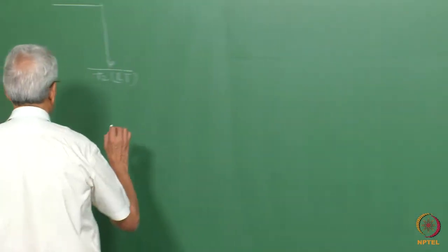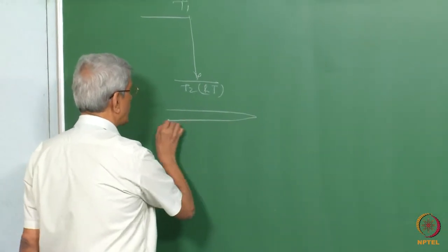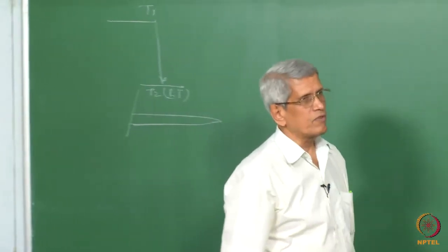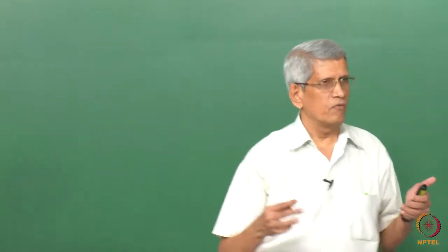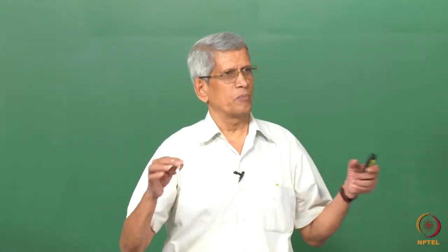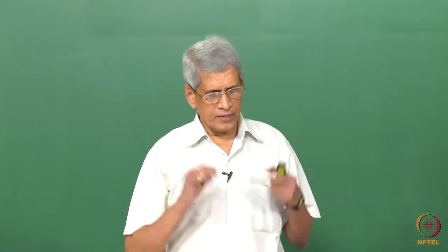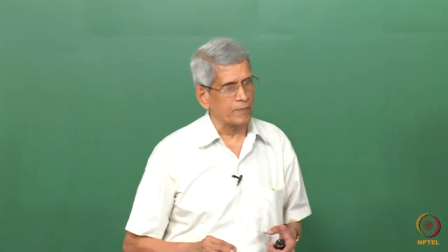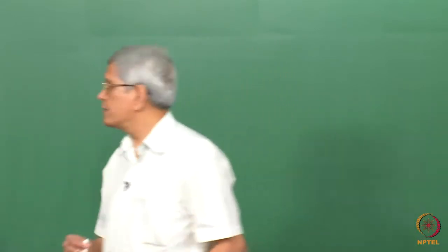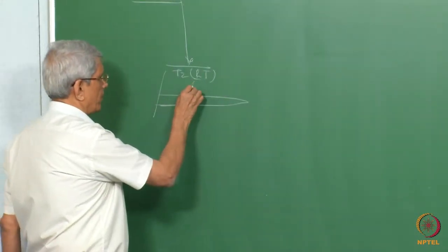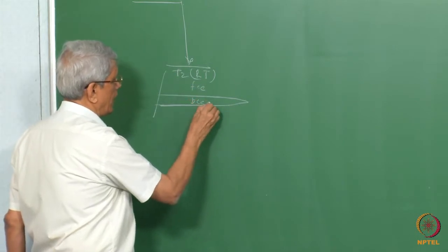What is essentially important is that when the sample is seen, some new phase has formed in the grain, which looks like a needle or plate shape, and the size of the plate is so large that if it grew by diffusion within such a short time, it is almost impossible. That means this transformation appears to be diffusionless, or diffusion does not play any part. The other observation is that this region has completely transformed from FCC to BCC or BCT.